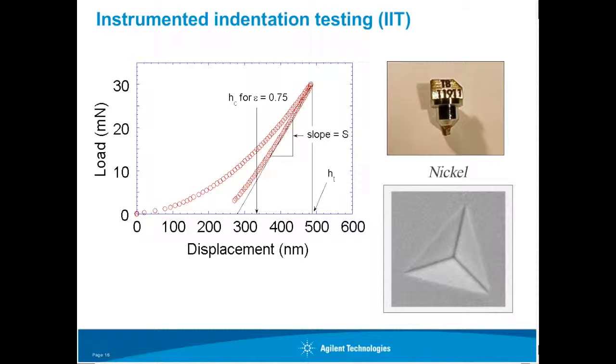All right, when we press the indenter into the sample, here I have a picture of an indenter. The very apex here is what gets pressed into the material. Depending on application, a variety of indenter geometries are acceptable, but the most commonly used geometry is a three-sided pyramid, and that has the name Berkovich pyramid.